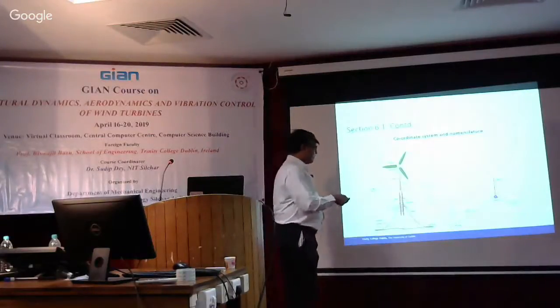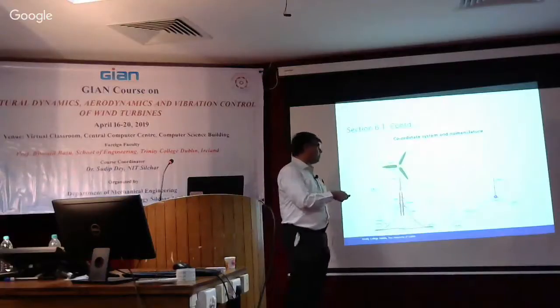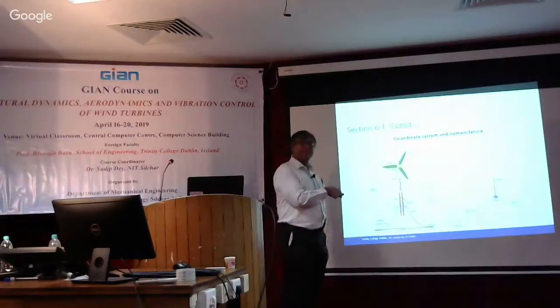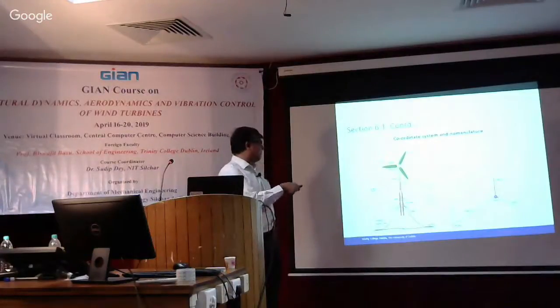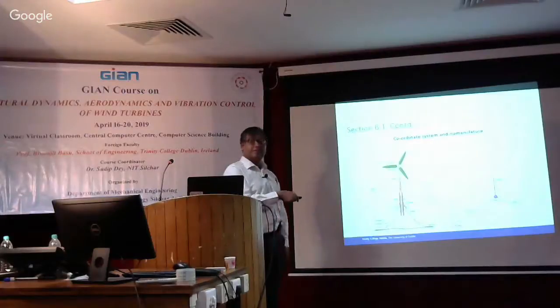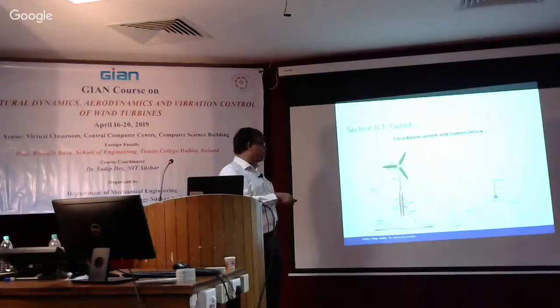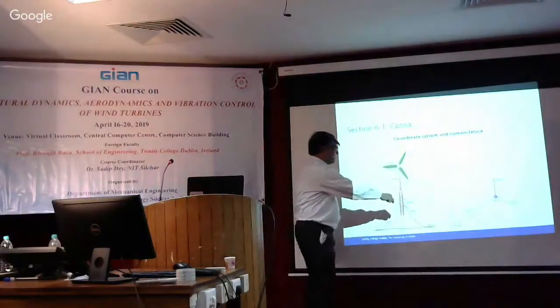Well, we'll come to that because we'll also have to talk about hydrostatic stability and hydrodynamic stability. So it is not completely like that, because what is happening is that the buoyancy is statically supporting it constantly. So there is a spring coming from the buoyancy as well. So effectively, there's a spring connected here which is supporting it. Also there is lateral stiffness and rotational stiffness of the surrounding water. So it's not fixed in that sense because you have a fluid medium here.